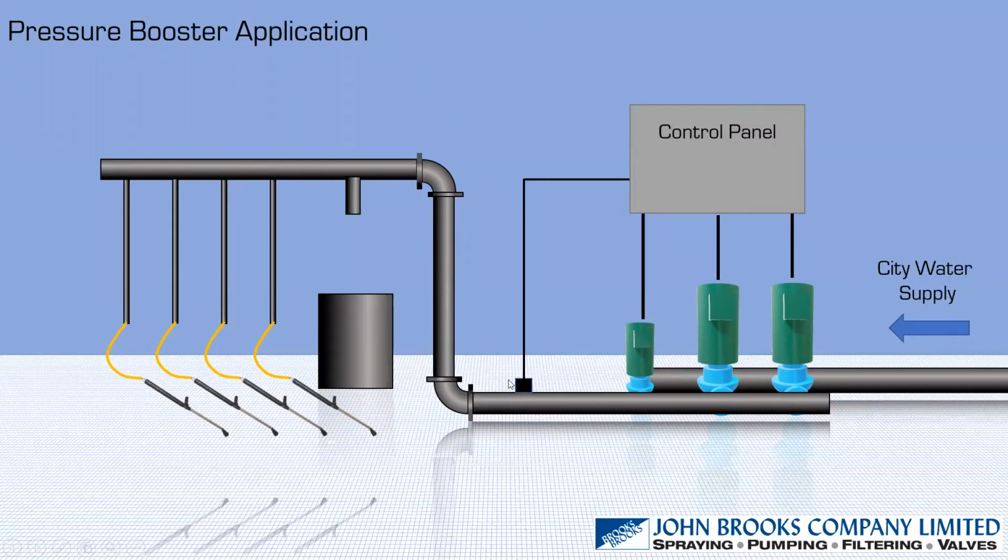And here is a pressure sensor. So what's going to happen when we start to use some of the fluid here? When one of these wands, kind of light duty, only a small percentage of the total flow is being used, well, we're probably going to get a pressure drop. And this pressure signal is telling us that there's a leak somewhere. Well, I call it a leak. Someone's using liquid. And therefore, we want to maintain a certain pressure. So what's going to happen is this small pump will probably come on first. And it will try and maintain a certain pressure. And it might eventually do that.